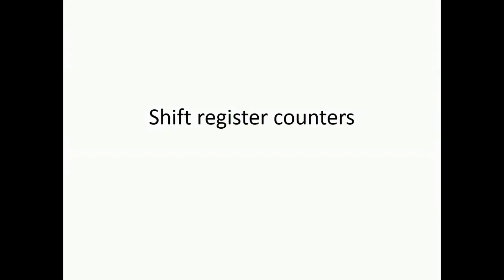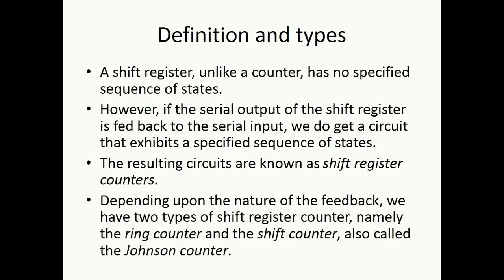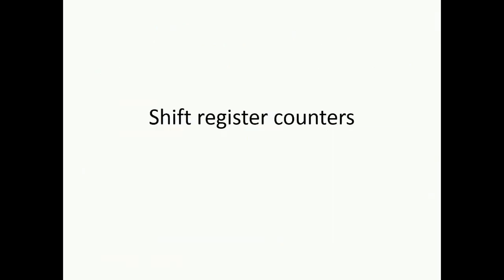In this video, I am going to talk about the shift register counters. What are the shift register counters? Unlike a counter, a shift register has no specified sequence of states. These are actually special types of shift registers in which we are going to see a specified sequence of states. That is why these are known as shift register counters.